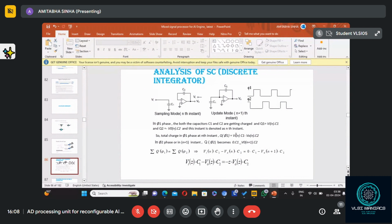Do you understand why it is minus? Because the output will be 180 degrees out of phase from the input. So if VI is positive, the output will be negative. It's simple. Q equal to C into V. So C2 into V naught N.